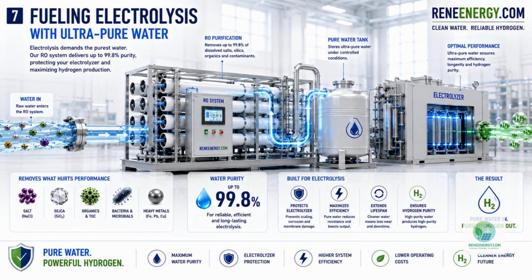Image 7 shows RO delivering ultra-pure water toward electrolysis. At this stage, the water has passed through the molecular separation process and is now much cleaner than normal feed water. It may still go through final polishing, such as deionization or EDI, but RO has already removed the bulk of the dissolved salts, silica, organics, and contaminants. The visual connects the RO system, the pure water tank, and the electrolyzer.